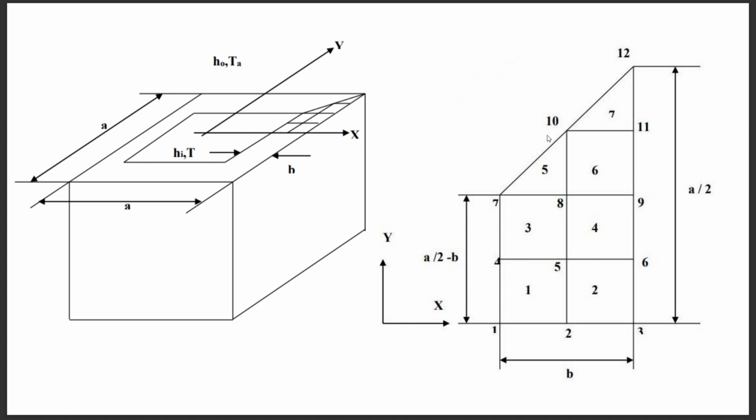First of all, we analyze this using ANSYS Mechanical APDL with the structured method. While performing the structured analysis, we can see that the object is symmetric along both the x-axis and y-axis directions. So if we divide the object into 1/8, then we can find some specific area. As a result, the results obtained from all of these cases will be equal.